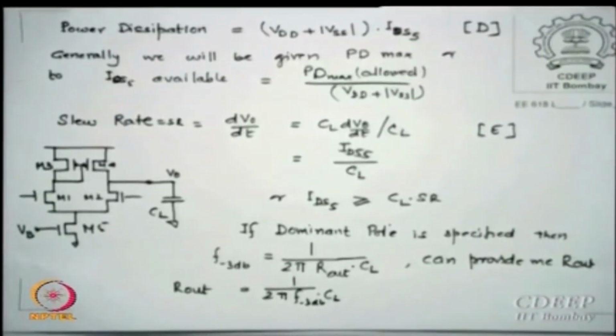So essentially it is decided by the change in temperature of the device, and we know around 150 plus the junction loses its junction property, and because of that no junction will remain as a junction, the leakage current will go so high that diffusion current will be dominated by drift currents. So we want to avoid that situation. So what do we do then? How do I decide that?